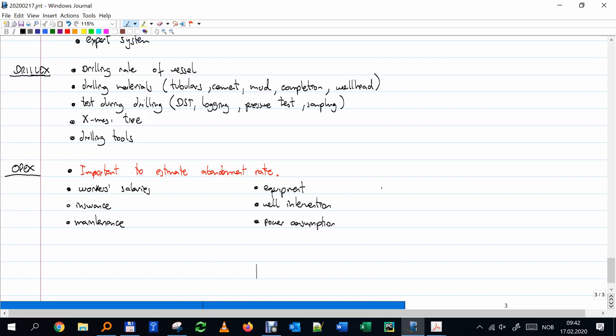Okay, and a big part of the cost is actually production chemicals. Okay, and we are going to talk a bit about that later, but actually all chemicals that are hydrate inhibitor, wax inhibitor, scale inhibitor, if I have a biocide, I have corrosion inhibitor, demulsifier, I have many chemicals that I use on the field. For example, that will be MEG, okay, wax,